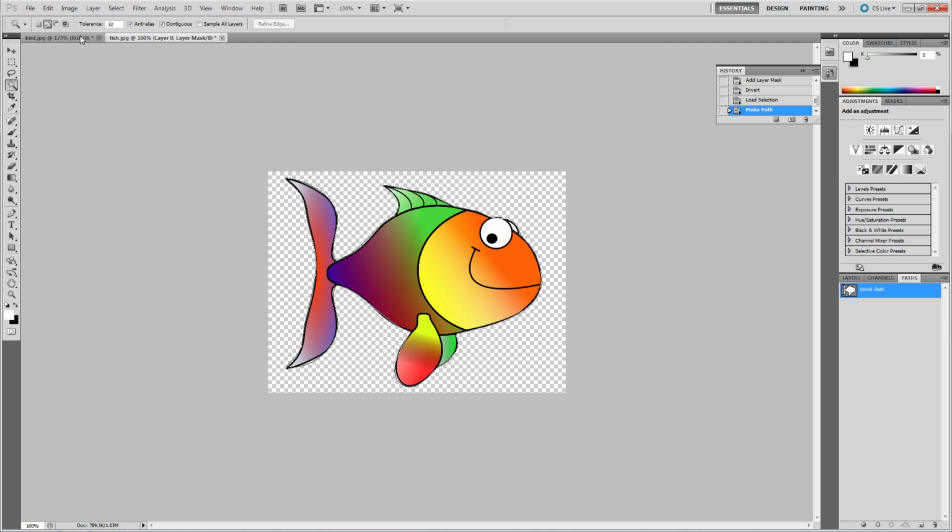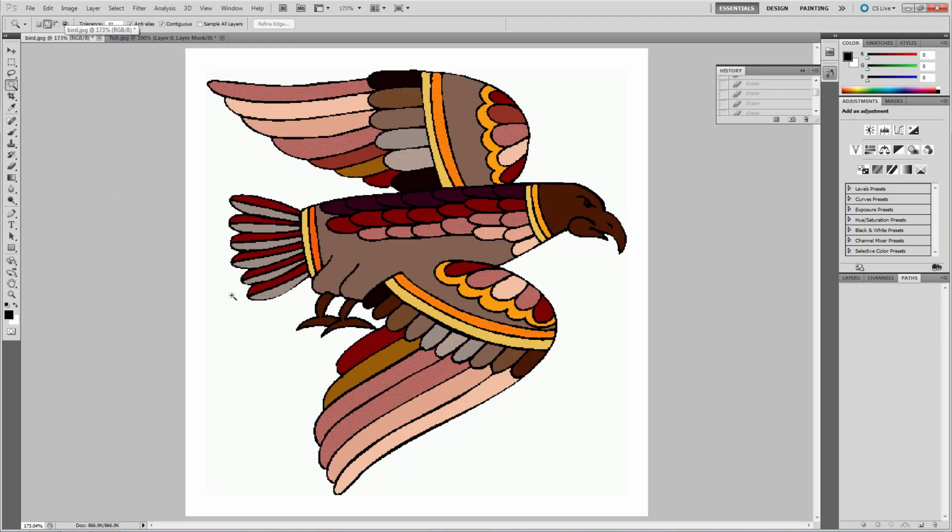All right, I'm going to want to look at this other image that I want to morph to this other image, like we morph from the square to the pentagon. We're going to morph from the fish to the bird. Now, this is the complex bird. If I select just the white, I'm not going to get these areas between its feet or here between its foot and its wing. Those will not be selected. If I add to the selection by clicking on this little button to add to the selection and click there, that will create 2 more paths. That's not what I want. I don't want to create 2 more paths. So you have to have one path.